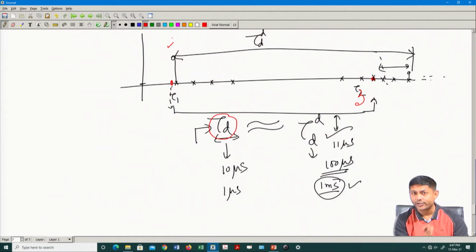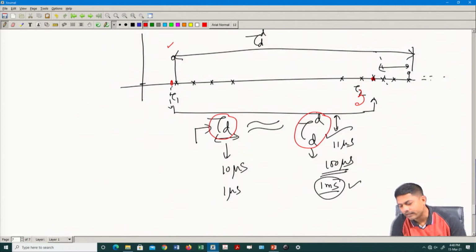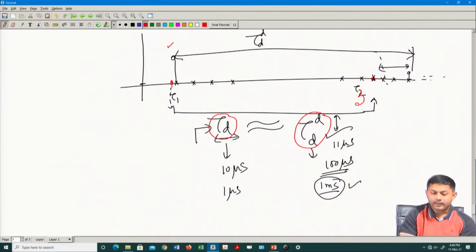So I have to pass through the ADC. The moment I pass through the ADC, the concept of tau d does not exist for me. What exists for me is the digital delay spread, that matters to me. So this is one definition of how exactly I will consider it, but as we notice they are of the same order tentatively. So we have learned delay spread.